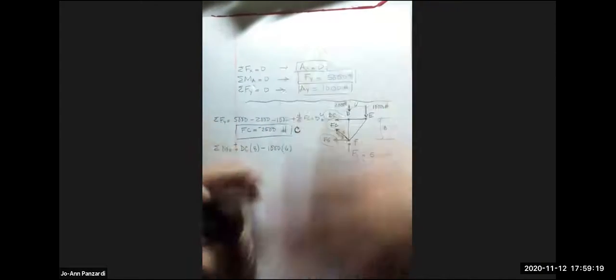So it's DC times 8 positive, 1,000 times 6 negative, and 5,000. See, it's a lot less work. So DC turns out to be, what did I get for DC? 750. Matthew, it's positive. So tension or compression? Tension. Thank you.